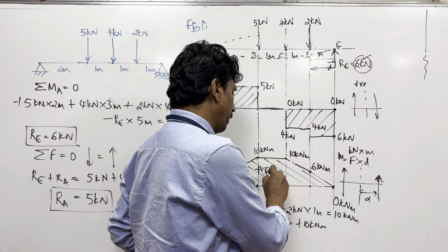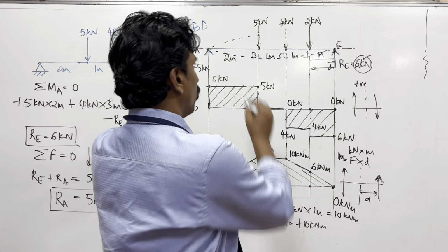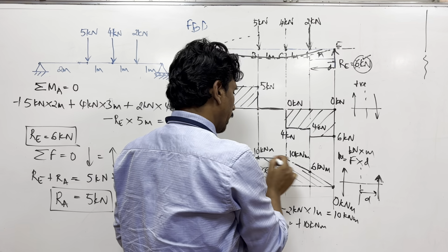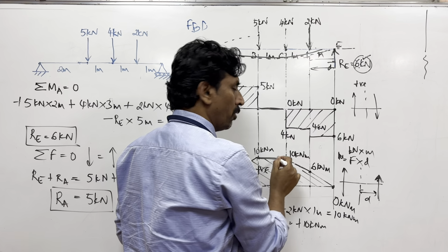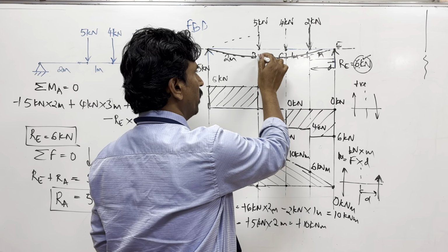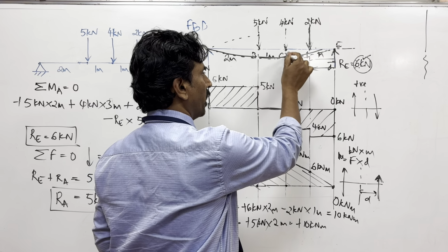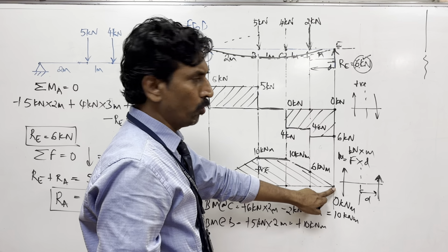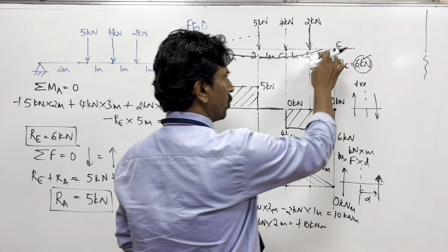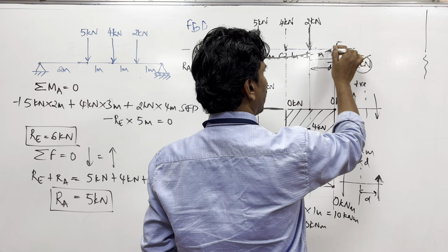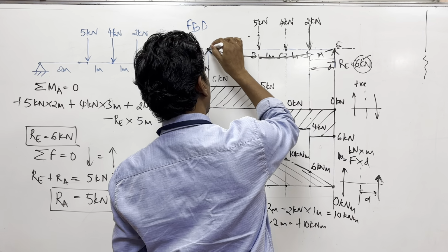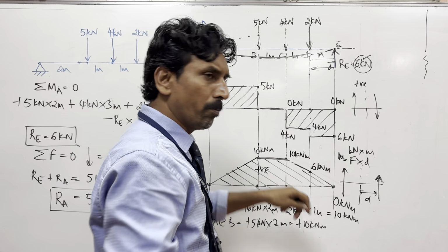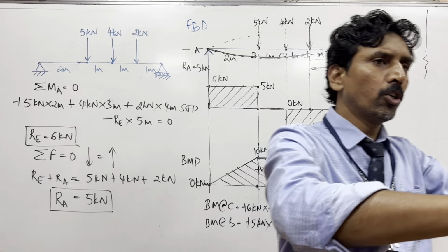Whenever you get a positive bending moment, that means throughout you will have the beam sagging here, and with a constant value of bending moment, between these points it will be an exact curvature. Very close to the end, the bending moment is almost zero, which means the beam would become almost straight here. It is very similar to your scale.